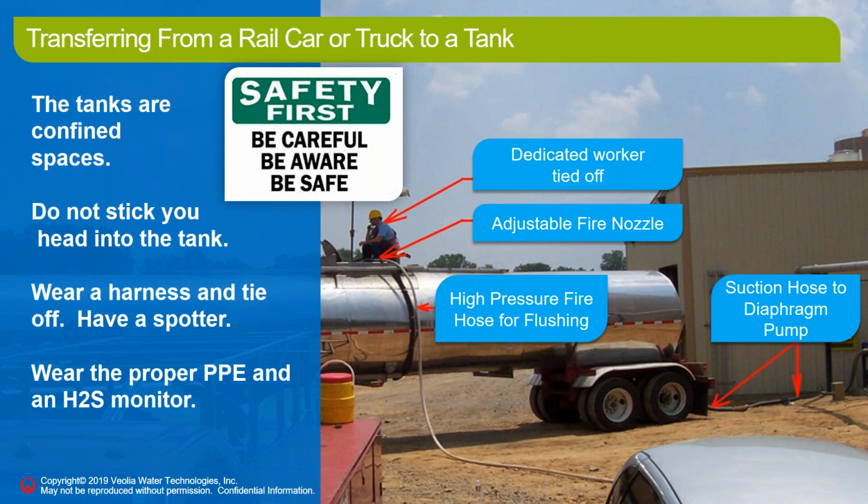Make sure you always wear the proper PPE. You have your safety glasses, gloves, hard hat, and an H2S monitor so you're not exposed to any harmful effects of H2S that may be coming off from the biogas that's going to be in the tank.